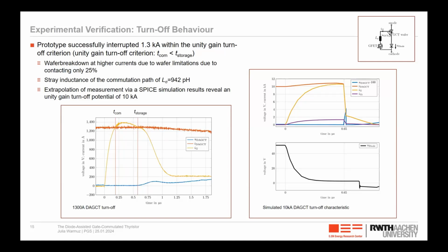So for IGCTs, you have some papers that say they have 2 nanohenries, others say 5 nanohenries. So it varies depending on your driver design, but under 1 nanohenry, I think it's a pretty small stray inductance.